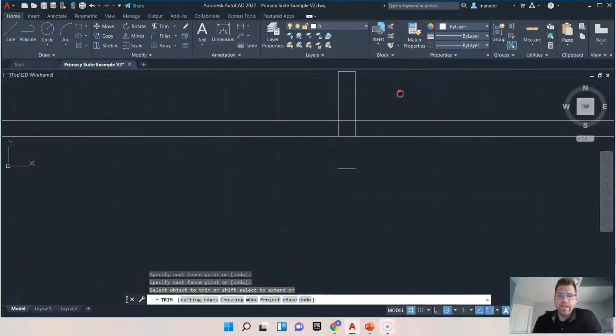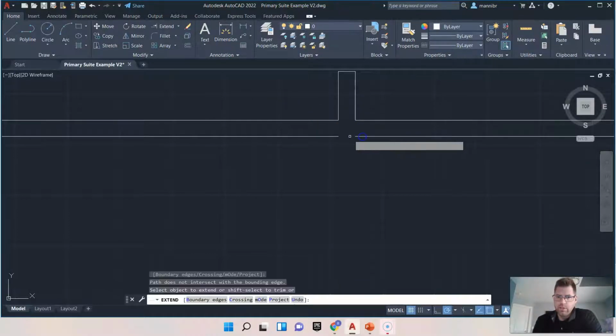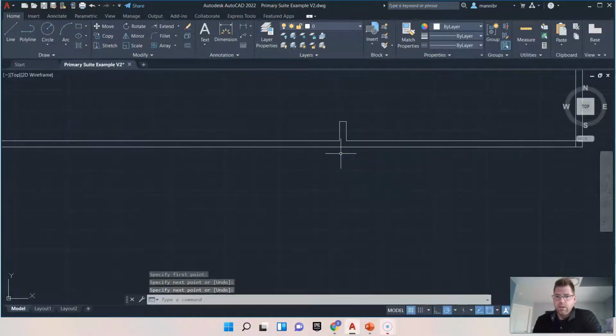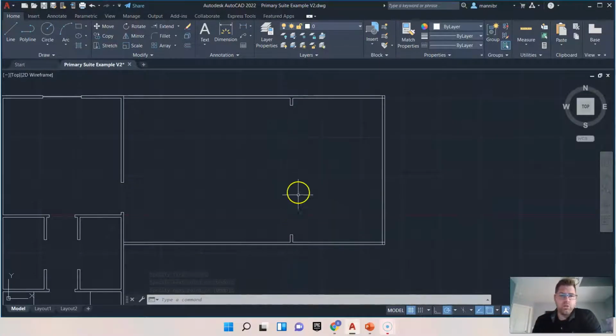So you're going to do a lot of that type of setup that I just did. Drawing some walls. Look at that, I went a little bit too far. So I can just run and extend, trim, extend. Sometimes I really like it when I make an inadvertent mistake, and I can show you that. Sometimes it bogs down the tutorial. So I like to try to keep it crisp as best I can. So I cut out a large opening, and we can put an archway in there. 20 feet minus 2, so around 18 feet. It's pretty big. We might need to add more distance from a construction standpoint, but we're not going to worry about that right now.